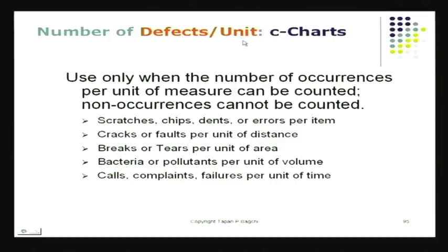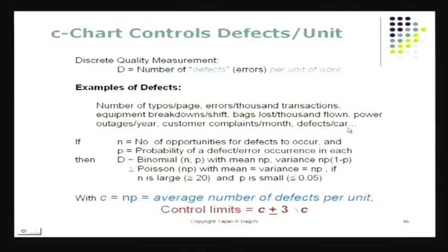So the unit you set in a manner that makes sense to you, find the number of defects you produce, and the rest of it is very similar. I will just remind you of one thing there. We are using the 3 sigma limit. In the case of x bar, we were able to comfortably use the normal distribution because the central limit theorem told us that the average approximates a standard normal variable, and therefore there is no real issue there. You could use the 3 sigma limit there.